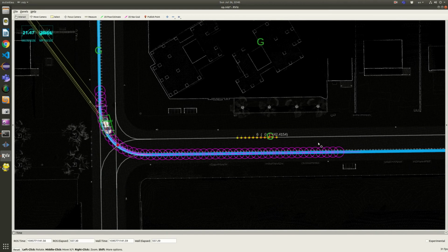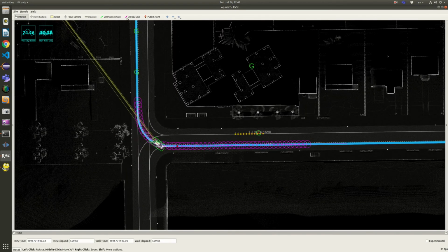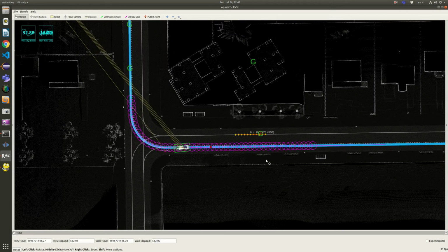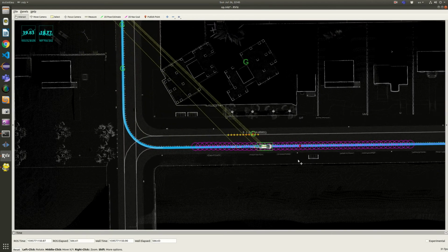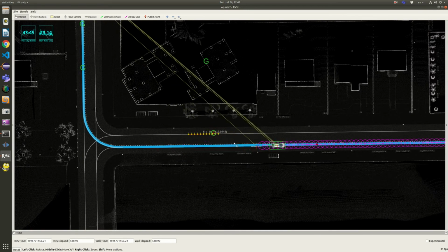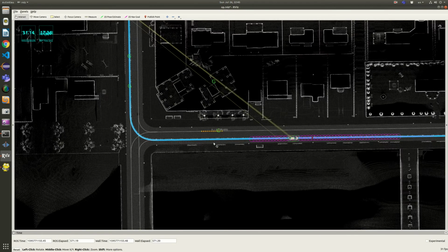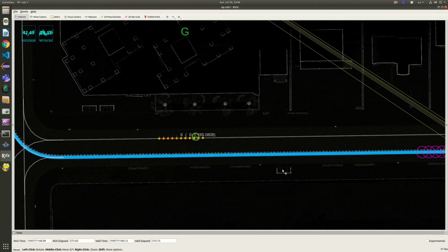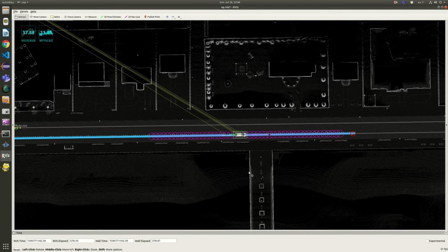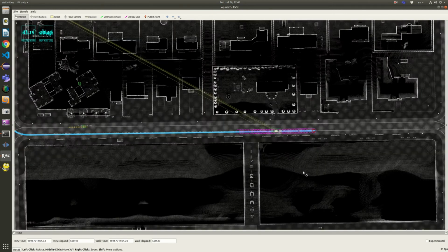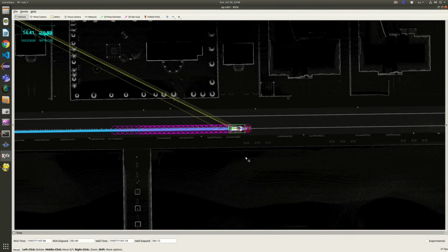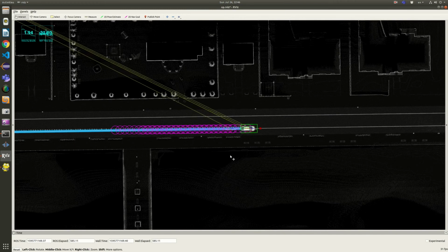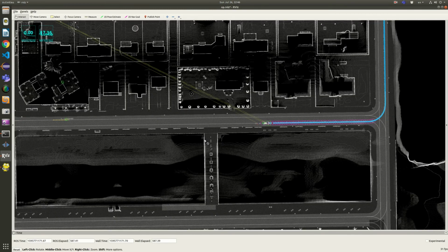Because we enabled multiple object insertion, it also inserts a goal for the global planner for each one, but it doesn't matter. Our global planner replanning option is disabled, so this will not have any impact on our testing. Let's fix the stopping problem for the obstacle and come back and test again.